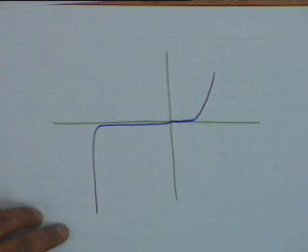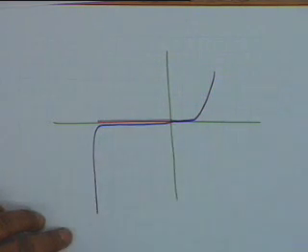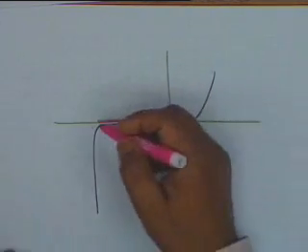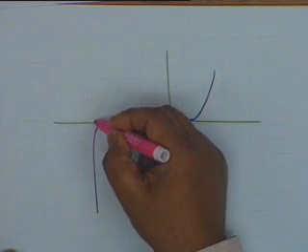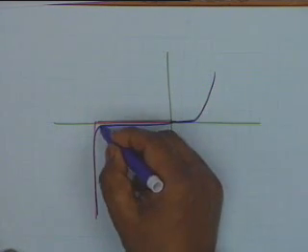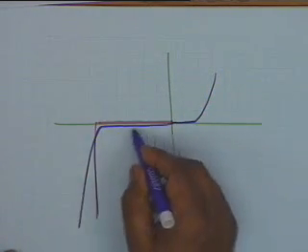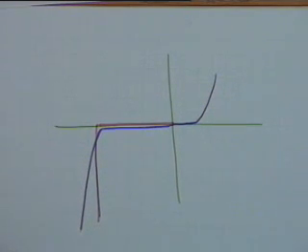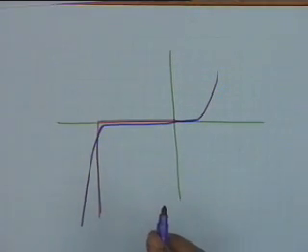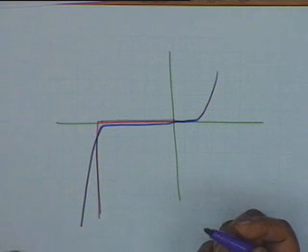reverse biasing condition, and one of the models that one uses is this, that is, one approximates this by means of zero current. Is is put equal to 0, and then a vertical line like this. I must tell you that the actual characteristic is like this, not a vertical line. This is the actual characteristic. It has a slope. It has a finite slope. All right. Now, how do you represent the Zener diode? What circuit model do you use for the Zener diode?